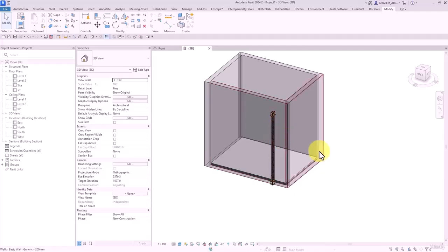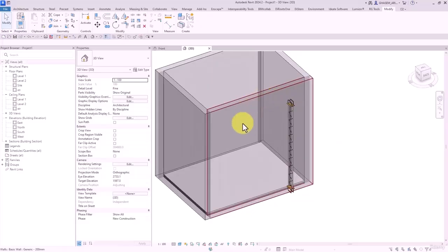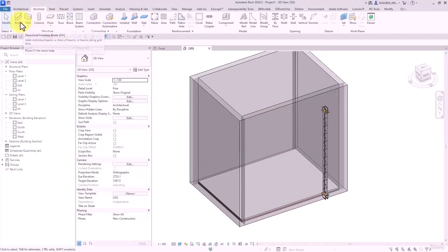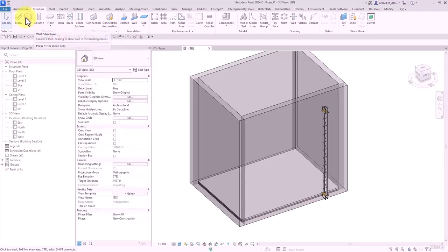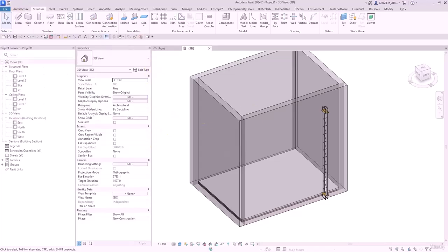So you can create the families of the wall posts as well. And you can control the number of details according to what you desire. For the people who are working in facades, there are some special details for which they can use these BIM tools, which are simple, and you should probably know how to use them. But sometimes you need to add some details to them according to what you desire.